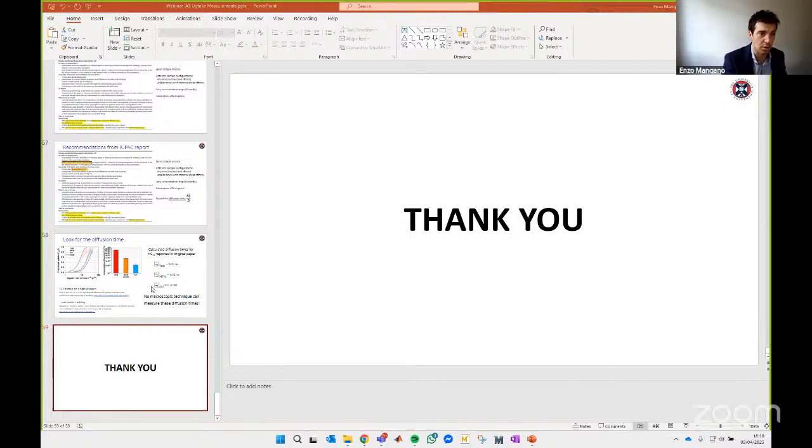then it means that you have a contribution of the valve in the very first, I don't know, second or fraction of a second in a fast system. What you want to make sure is that you see the tail of your time constant, which is very different from the kinetics of the flow through the valve. This allows you simply to inspect the experimental data and see if you are in a situation where you are completely controlled by the valve.